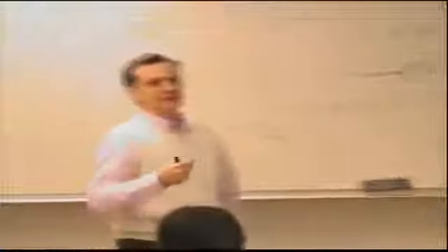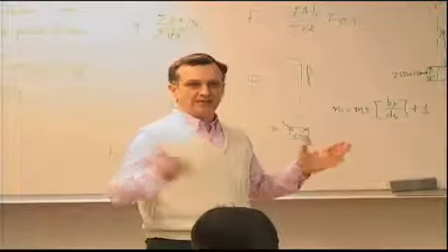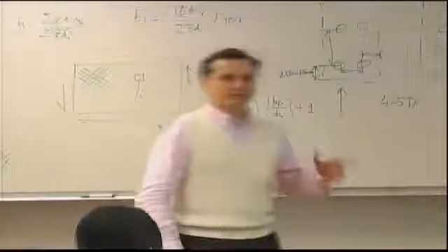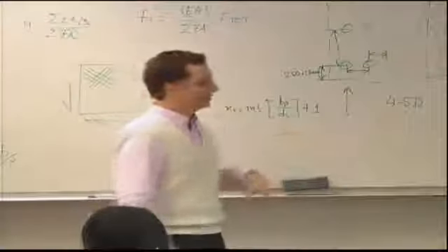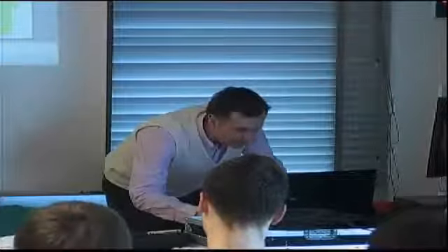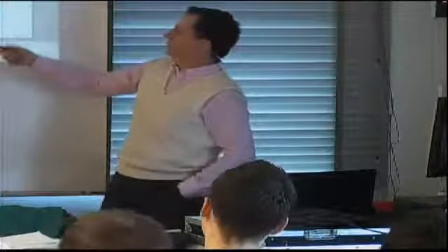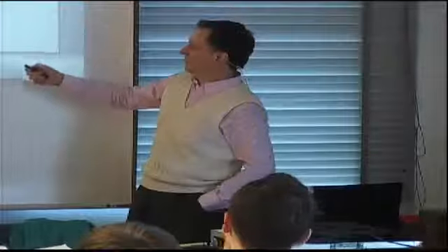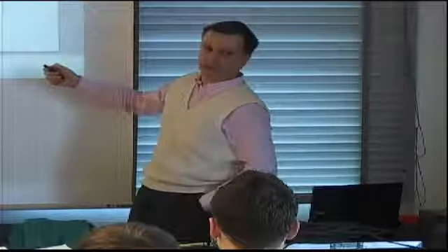What's the membrane stiffness, the EA, which you can represent as the A matrix, because the A matrix is EA divided by width. We showed way back, last lecture or the lecture before, that if I have a whole bunch of members under uniaxial loading, the equivalent EA for all the members is the sum of the individual EAs.